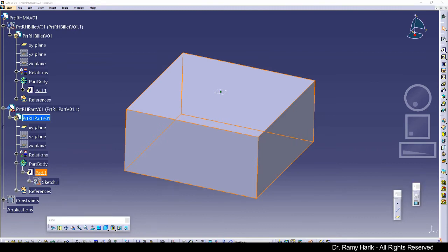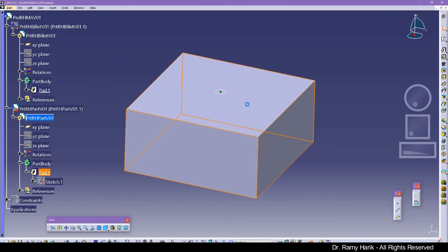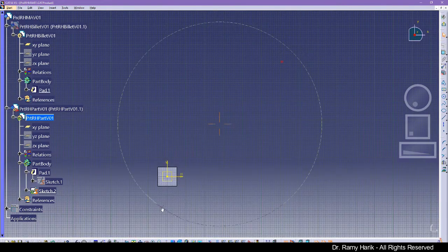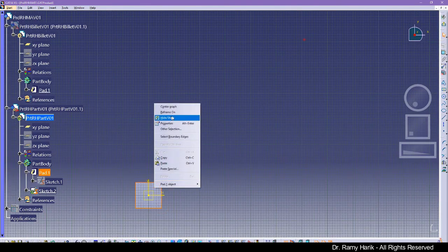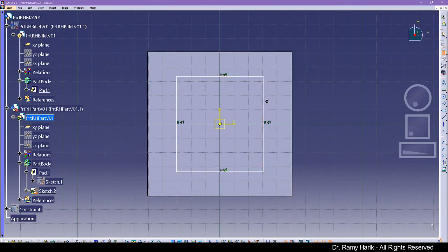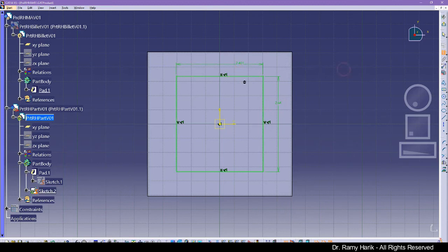The second thing we want to do is create a 3x3 pocket. So we're going to click on the surface. If you click fit all in, it will fill everything else. If you right click reframe on, it will bring you back to this point. So I'm going to show you another way to set everything else to 3 inches.